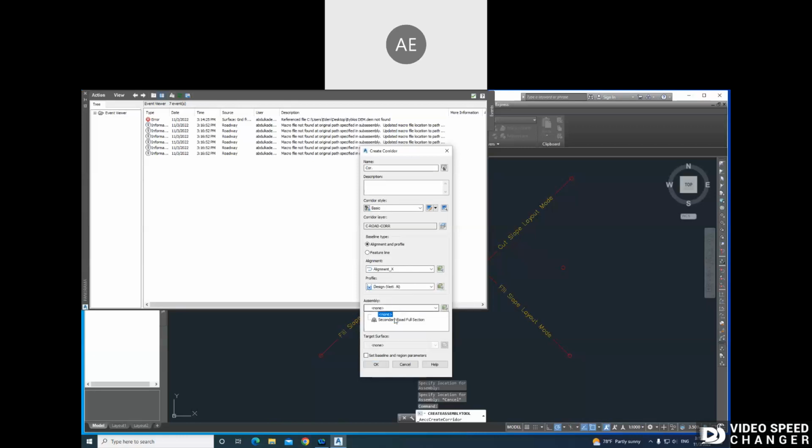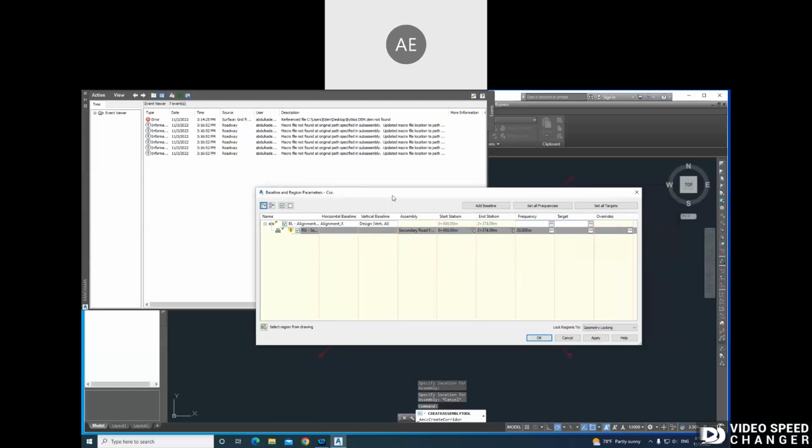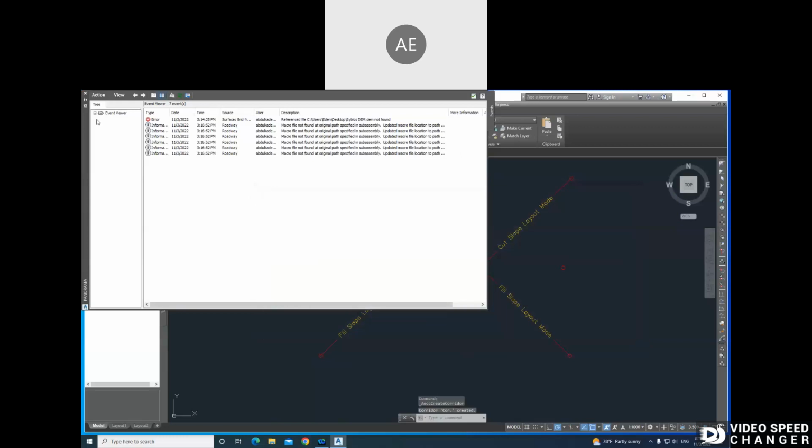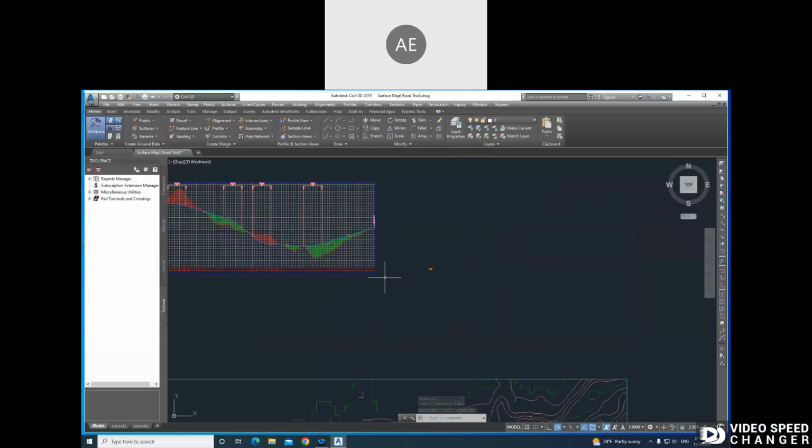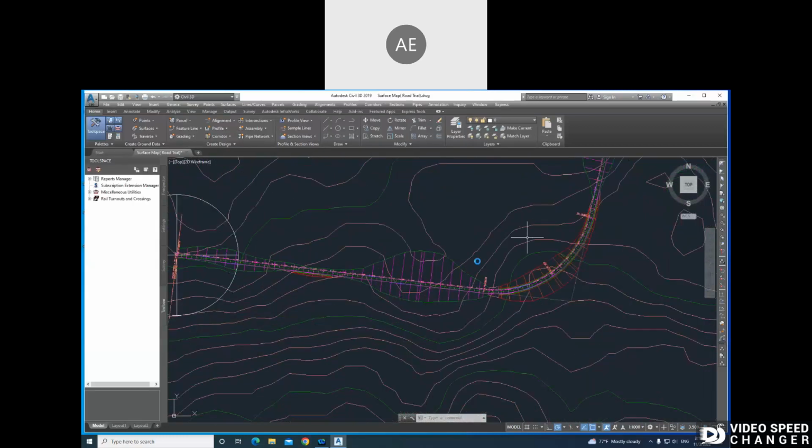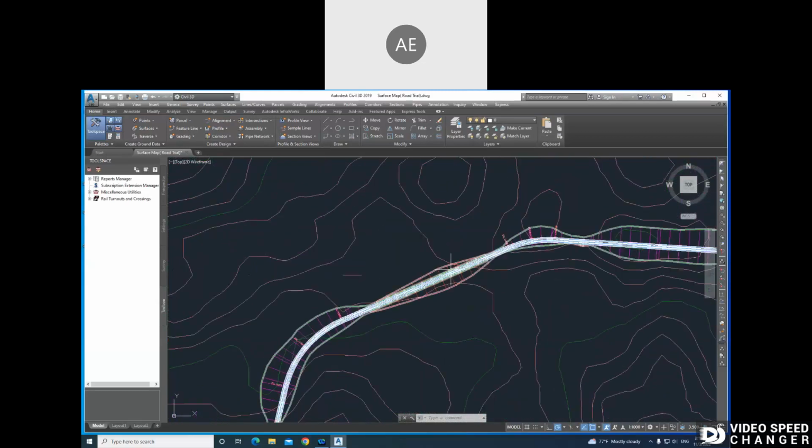Of course, this is the secondary road full section. This one that now we just created the assembly as you saw, and we have the original surface available for execution. So we press OK. Now we have the alignment ready. It starts at the station, it ends here. We simply press OK, and we ask to rebuild the corridor. So the corridor, as you can see now, if you go to the alignment, the corridor has been already drawn by the software. You can visualize the area of cut and area of fill.